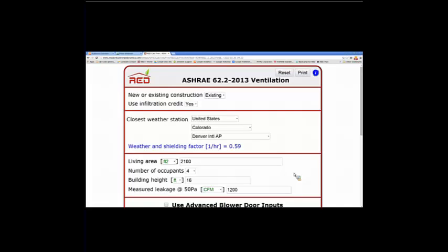If you are following the ASHRAE standard, Appendix A states clearly that if it's an openable window on a bathroom or a kitchen, you may reduce the deficit for that bathroom or kitchen by 20 CFM. It's very clear in the standard, and it does not say there that it's up to the authority having jurisdiction, as I recall.